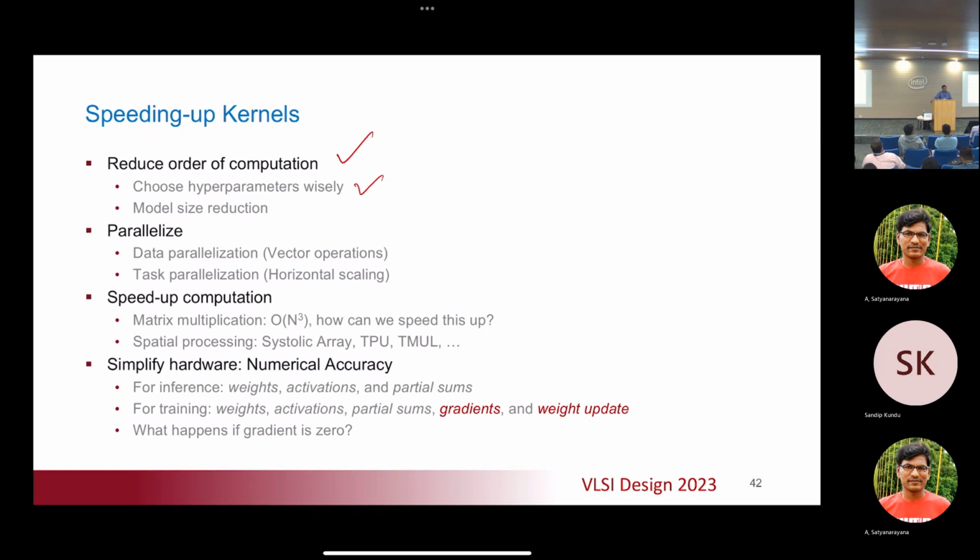If you do TPU, for example, you have very large area, you have very large power consumption. On the other end, if you try to do something like the traditional Qualcomm NPU approach, then you take a much smaller vector in terms of parallelization, because you're trying to also fit within the power envelope, which for the mobile processor has been stuck at 5 watts for a long time because your mobile battery capacity has not been increasing. And so you really cannot spend any more power than 5 watts during peak computation in mobile processors.